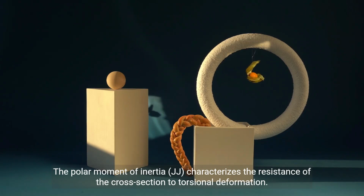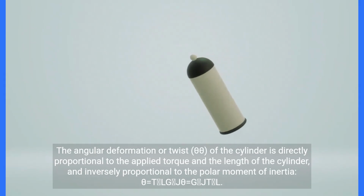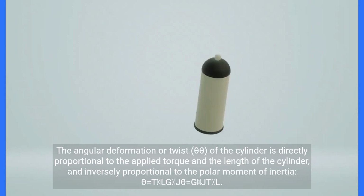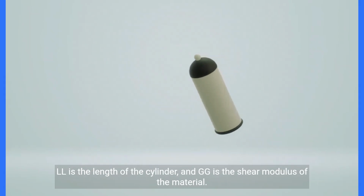The polar moment of inertia, J, characterizes the resistance of the cross-section to torsional deformation. The angular deformation or twist, theta, of the cylinder is directly proportional to the applied torque and the length of the cylinder, and inversely proportional to the polar moment of inertia: theta = TL/GJ. L is the length of the cylinder, and G is the shear modulus of the material.